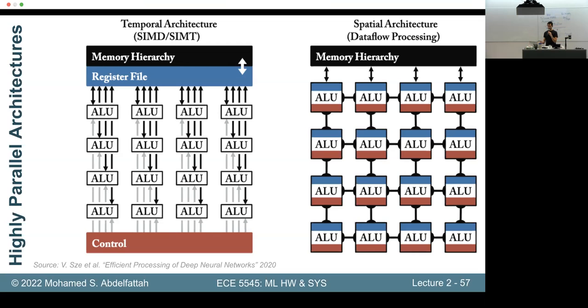Usually how it's organized within an accelerator chip is like this. We would have some kind of memory loading a register file, and then once data is in my register file, it gets broadcast or forwarded to all of the ALUs. The result would be computed, and then written back in that register file, which can then be used again by all of the ALUs.